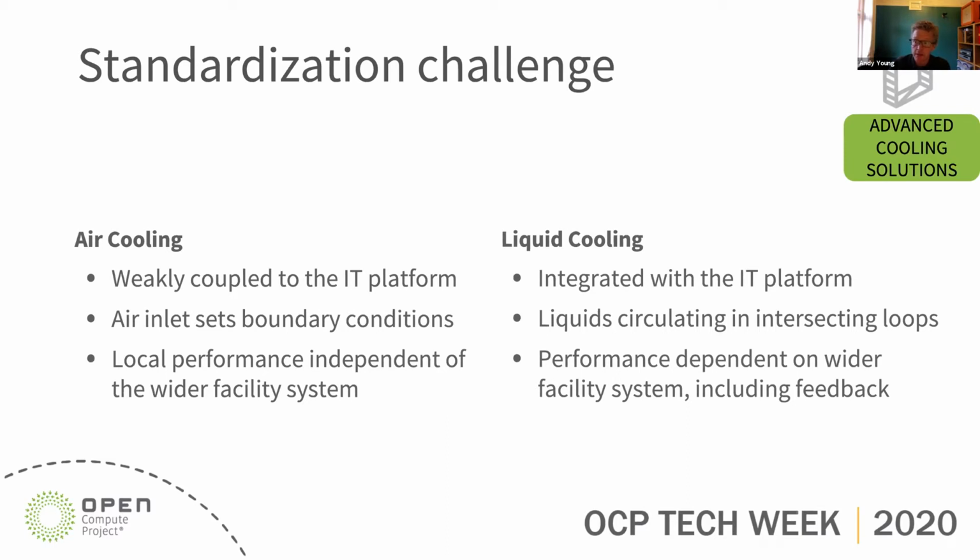When we look at liquid cooling solutions, we find a different picture. So the same three points, but the antidote to those really is that the IT platform's more integrated with the cooling solution. Think of immersion cooling, for example, but also closely coupled cold plates, more close coupling, no buffer between them, physical contact, physical immersion. Liquids involved, multiple in many cases, and flow in intersecting loops. So therefore the performance is dependent on the wider facility, and the intersection means that there is feedback, the outflow from one being the inflow to the other. So interdependency and feedback occurs in advanced liquid cooling solutions. So for this reason, standardization is challenging. Not to say we can't do something about it.